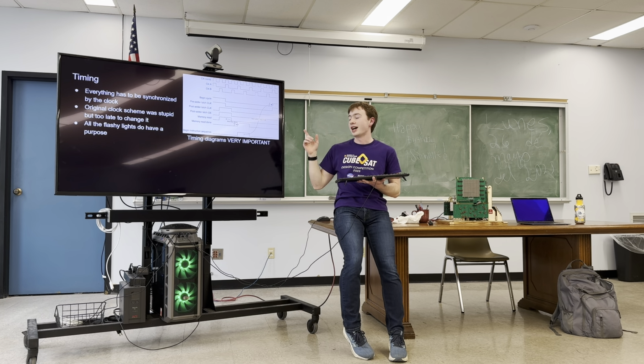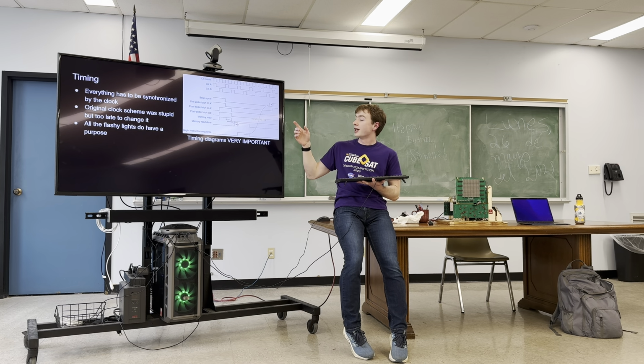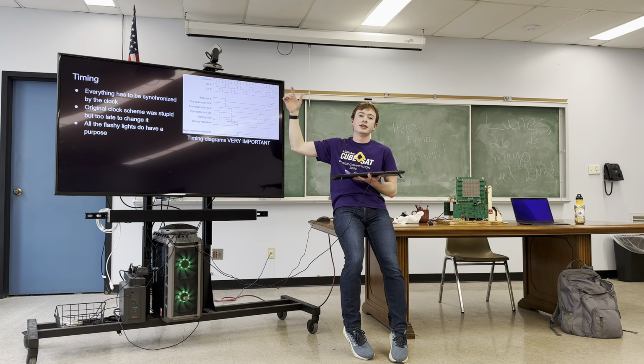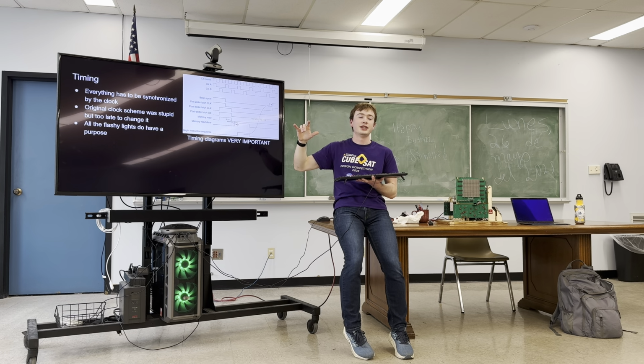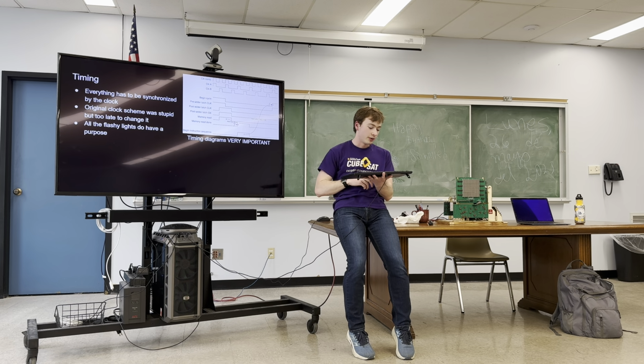Like on the latch that I showed earlier, if the data input goes high at the same time as the clock, then it's not really possible to predict what the output would be. So if I have one part of the computer running on just the B clock and the other part running on just the A clock, and they communicate with each other, then there's no chance that they would ever try to do something at the same time.